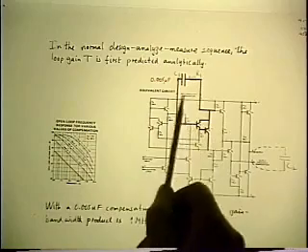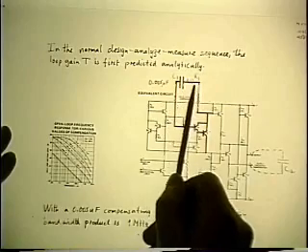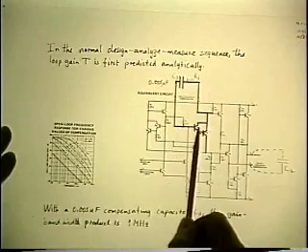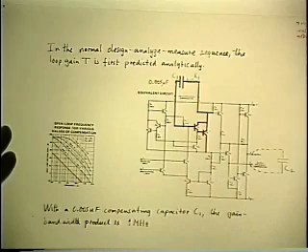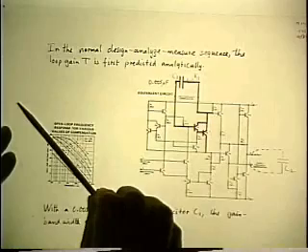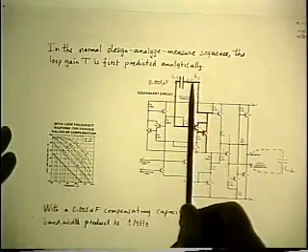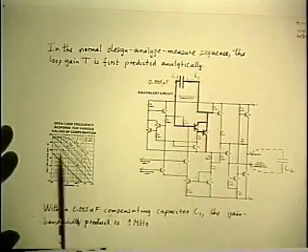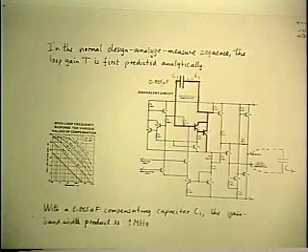So the IC chip designer said, when you put a capacitor of 5,000 there, you'd better put a resistor of 1.5 K as well in order to give a 0 in the response, in order to cancel a 22 kilohertz pole that is somewhere else. And that's why it doesn't show up, because it was purposely designed to cancel it out. But when I neglect to put that resistor in there, that 22 kilohertz pole, which is somewhere else, is no longer compensated, and it showed up in the result. And that's what made it go unstable.